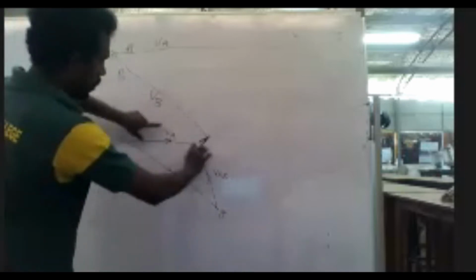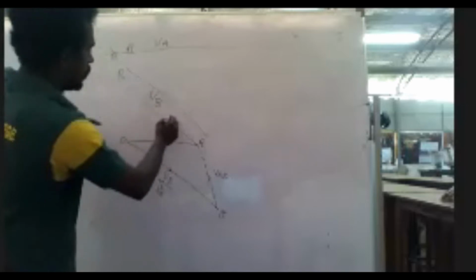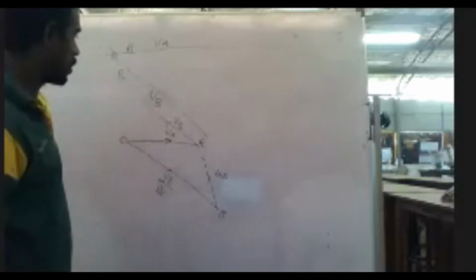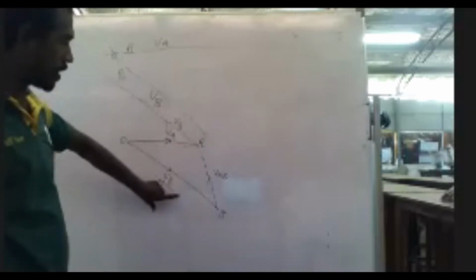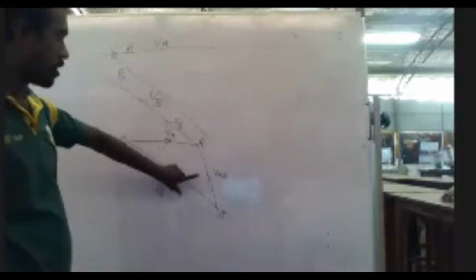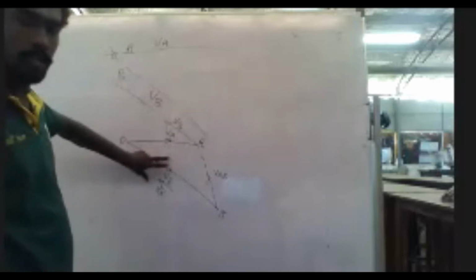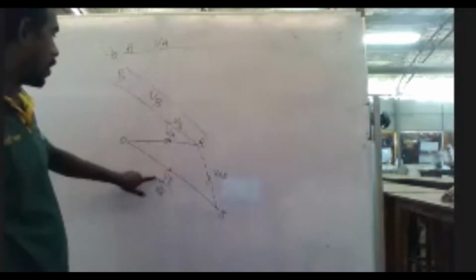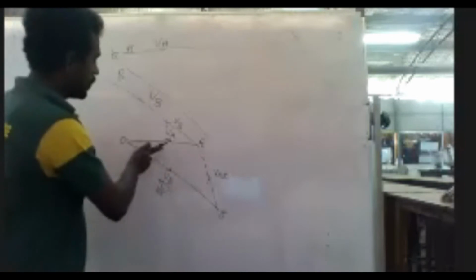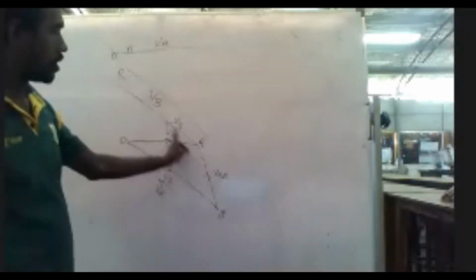So at this particular angle, I'm going to apply a velocity VB for A also. Here also I am applying VB to stop this. The same VB I am applying here also. So now this VB is stopped. This is not moving. Now I have a velocity VA this way, and I have applied another velocity this way.